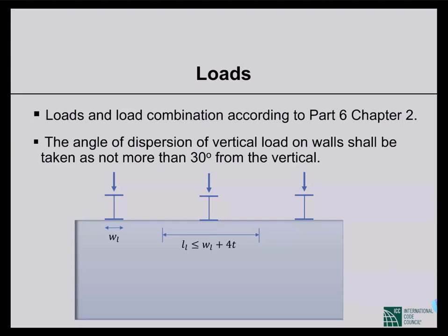The loaded length will be the center to center spacing of the beams, but this cannot be more than the width of loading shown in the picture, that is the flange width of the beam or the bearing width of the beam, plus 4 times the thickness of the wall.